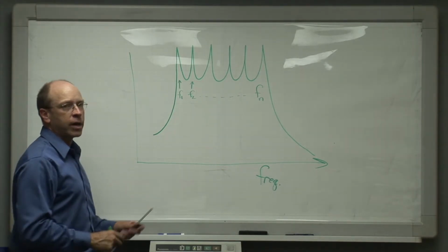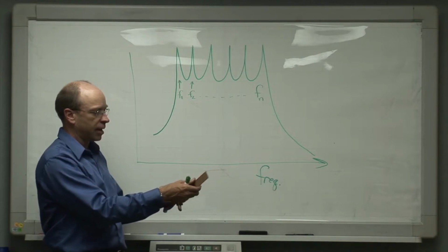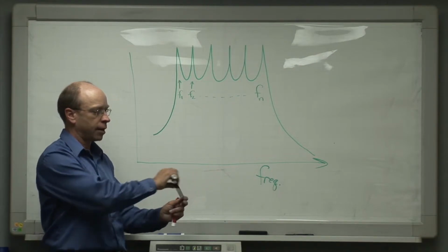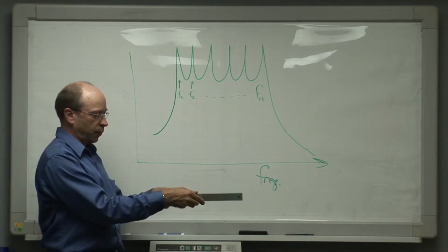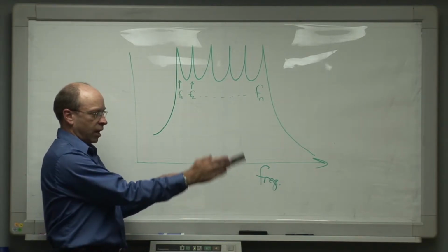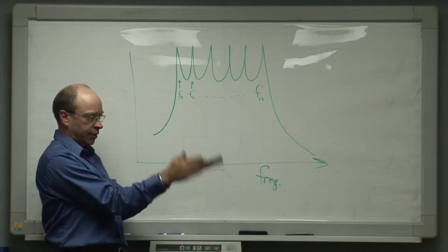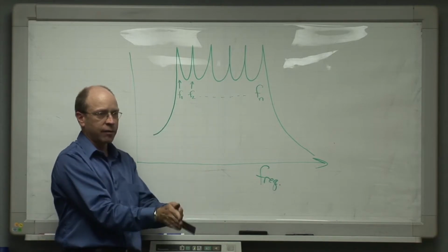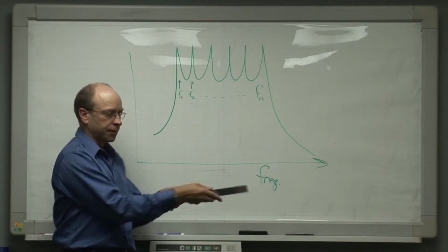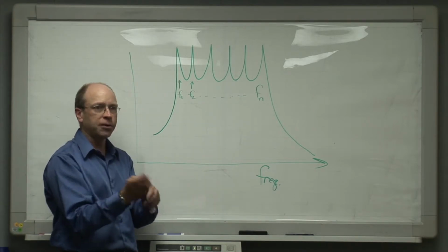While it's doing that, we know that the radar beam itself is scanning through space like this, if it's a simple air traffic control radar, and if it's a three-dimensional radar, the beam in fact may be doing this behavior, coming up in elevation angle, then turning off and dropping down, coming up in elevation angle, turning off and dropping down, and so forth, as it's rotating in azimuth. That makes it even more complex. So we're changing frequencies while we're changing azimuths, while we're changing elevation angles, all simultaneously.